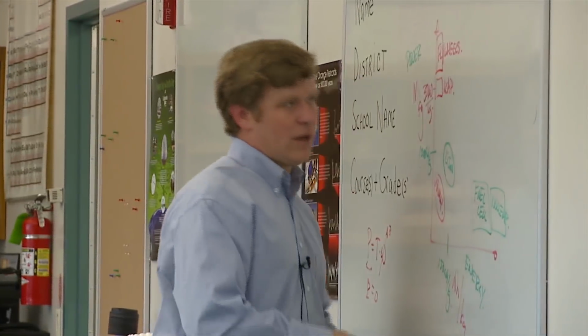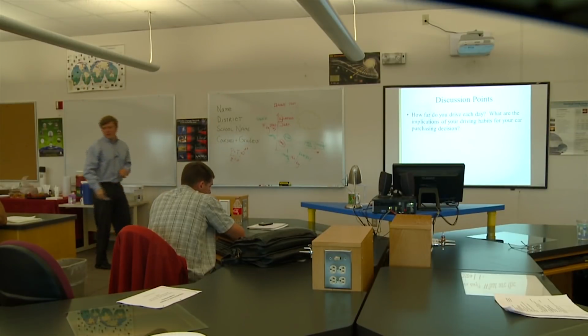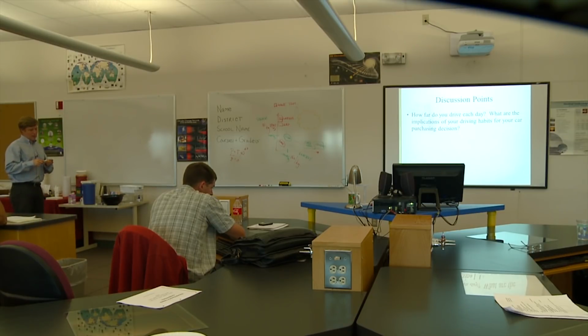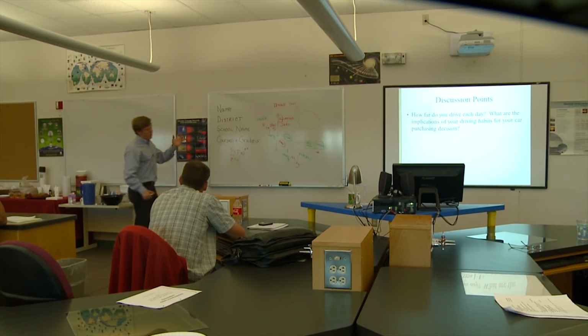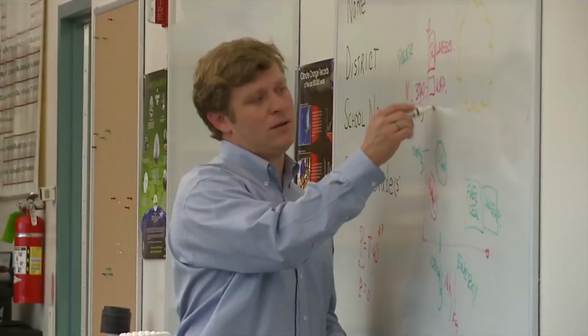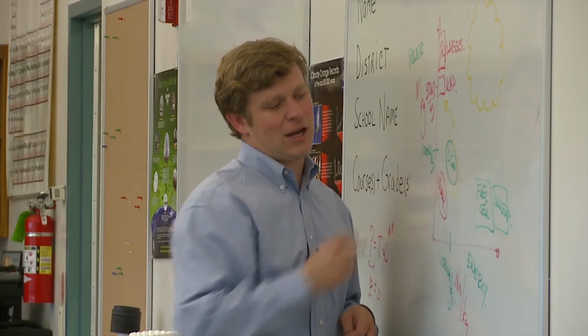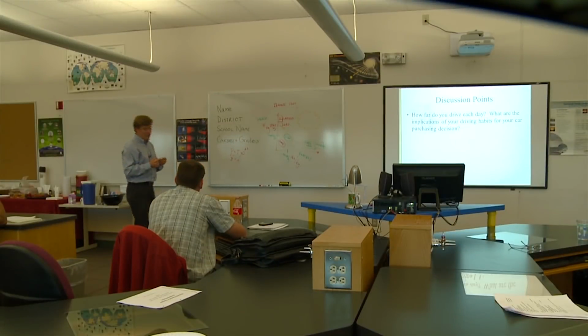So the problem is everybody would all love to have something that would operate in here, right? But the fates have conspired against us to not leave us with that chemistry or technology or anything else like that. But everybody's trying to get there. So part of the thing is that flywheels, ultracapacitors, hydraulic hybrids sort of are up in this area here. They have lower energy, higher power, and batteries kind of occupy what you might call a sweet spot, that they have the right amount of energy to power ratio.